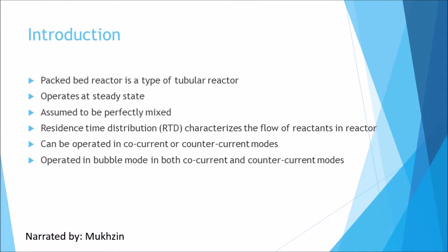A packed bed reactor is a type of tubular reactor where reactants flow through the reactor through packing without radial variation in reaction rate. It operates at steady state and is normally assumed to be perfectly mixed without dependence on any variables in the reactor. In cases where non-ideal mixing and unsteady state behavior are investigated, residence time distribution is used to characterize the flow of reactants in the reactor.